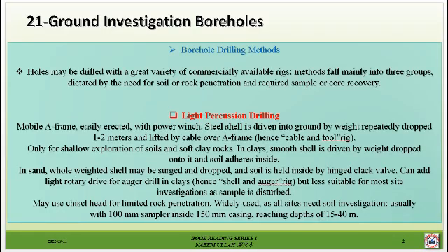Section 21: Ground Investigation Boreholes. Borehole drilling methods. Holes may be drilled with a great variety of commercially available rigs. Methods fall mainly into three groups, dictated by the need for soil or rock penetration and a required sample or core recovery.